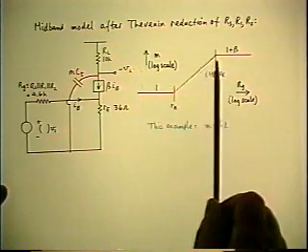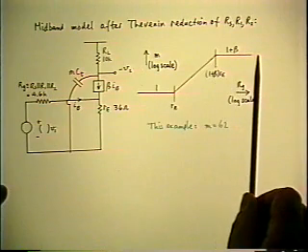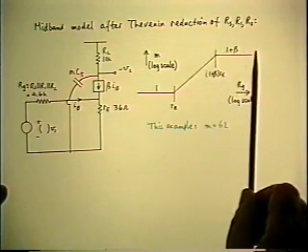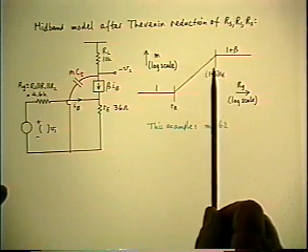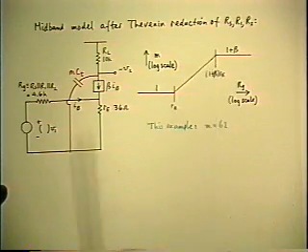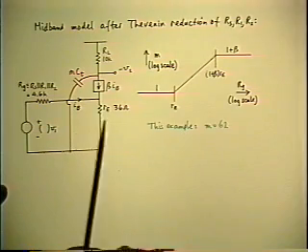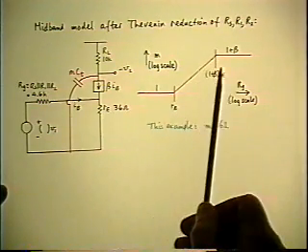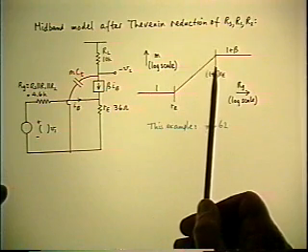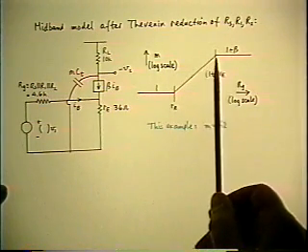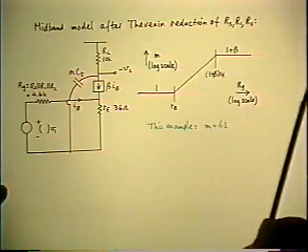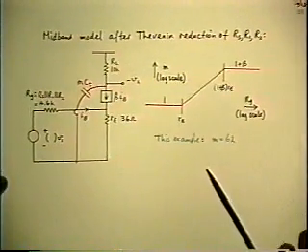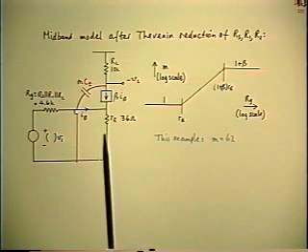So the M is 6 dB down below the 1 plus beta, 6 dB or a factor of 2. The beta was 120. Half of that is 60. And M is 62. So that's consistent with what we've already said about this interpretation. So in this example, we happen to be just about right on that corner. So as a high-frequency amplifier, this is a lousy design.